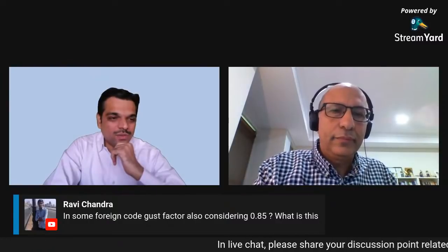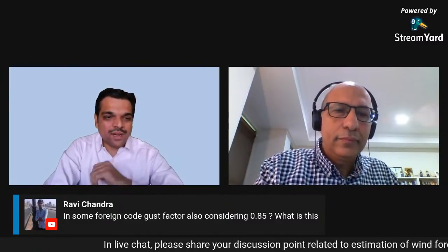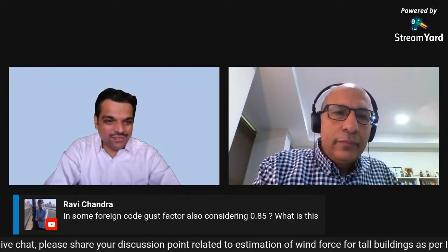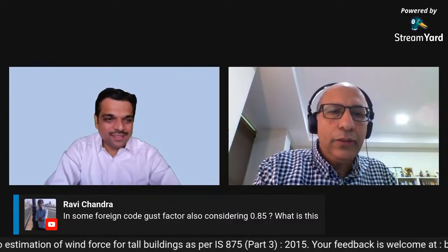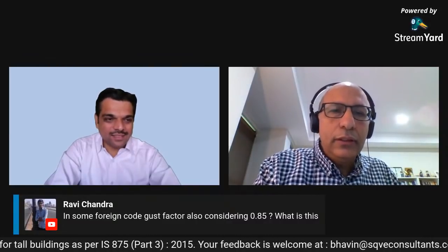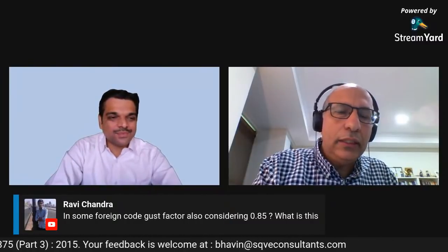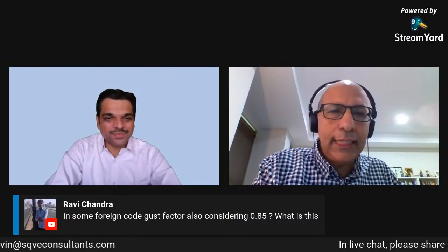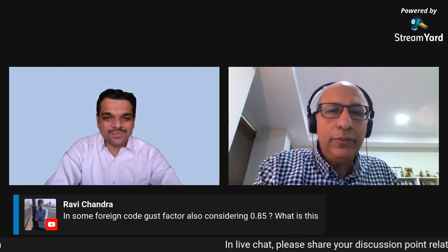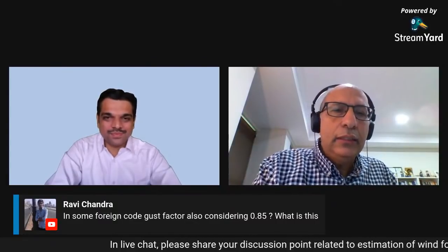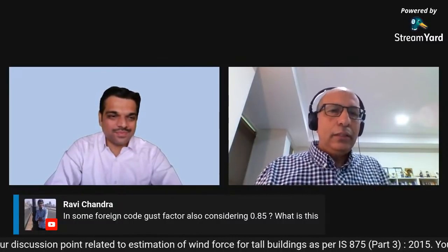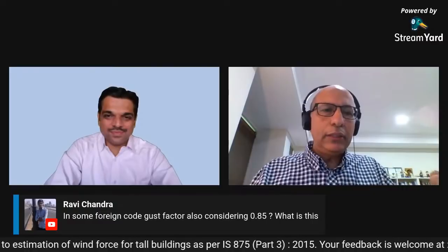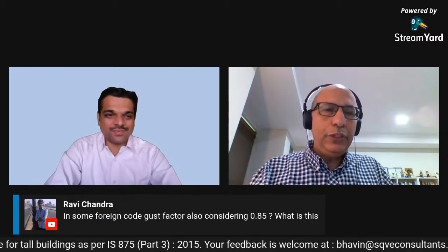Okay, this is a question from Ravi. In some foreign codes, a gust factor is also considered as 0.85. Can you throw some light on this? Oh no, that's not a gust factor. The 0.85 is an effective direction multiplier. For example, the ASCE has a 0.85 prefix. By the way, the coefficients in the ASCE combine the capital G, the gust factor, with the coefficient in one.